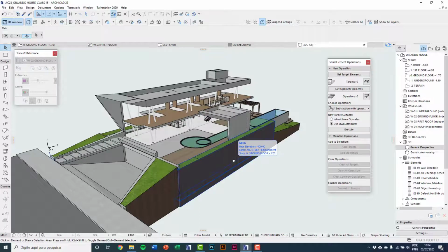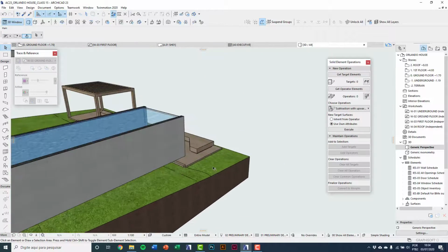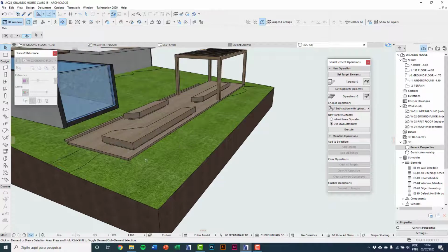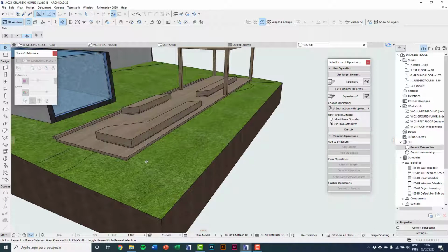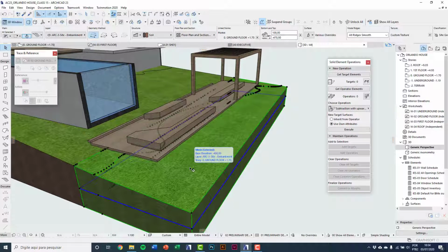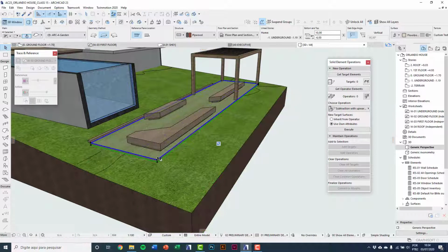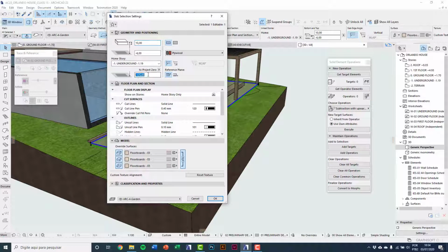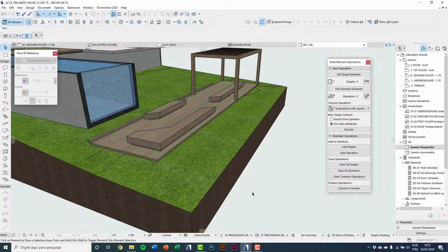Now I'm going to do the back part, this part near this wood deck. Here I will have a plain grass area, select the deck and check the level, which is -125. So I will elevate mesh points to 130, 5 centimeters below. Going to terrain.